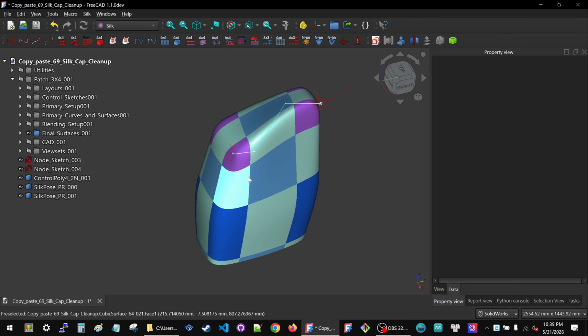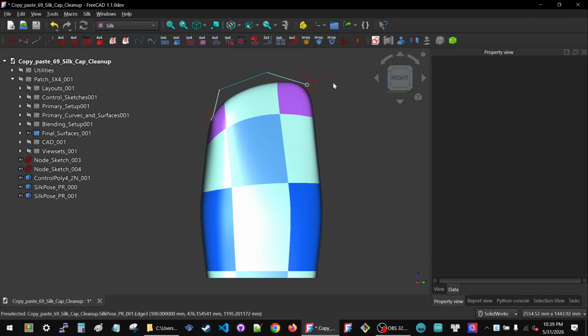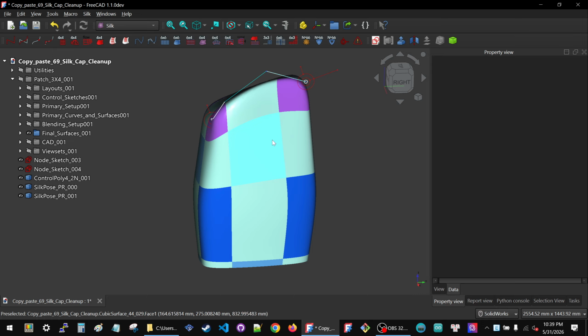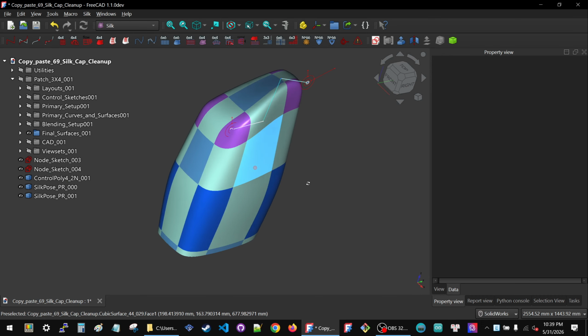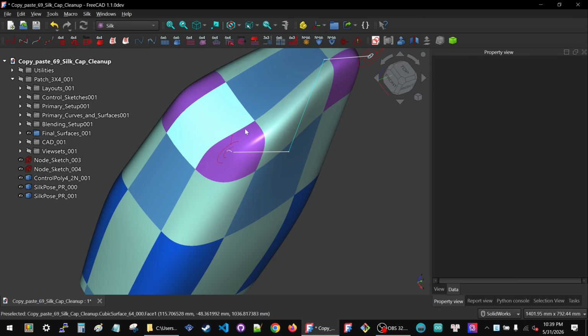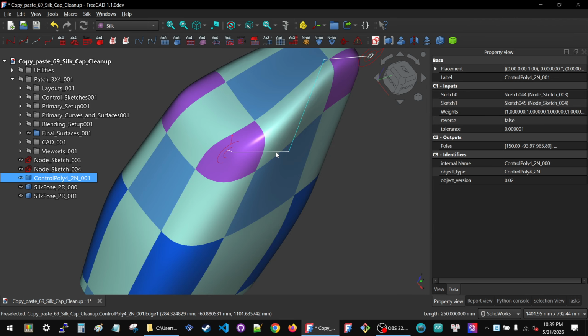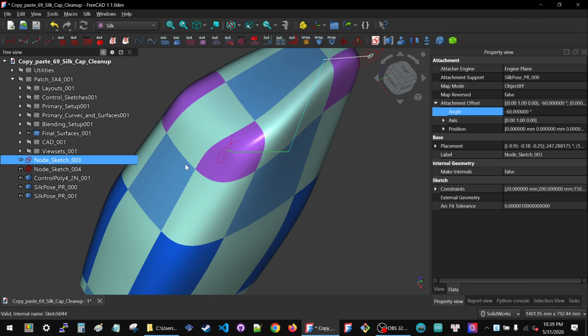But here we go. This is a 3D sculpting system where most of the time you should still try to work in a plane, as long as it's possible to do so. And you can have your planes be offset to each other and have really simple way to navigate across them. But if you want full 3D, you can either use FreeCAD attachments, but now you have a way to do it where things are deterministic. This will always be 60 degrees in the same direction.